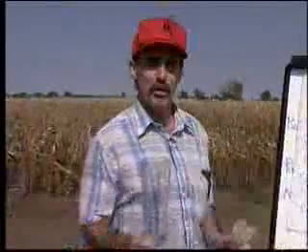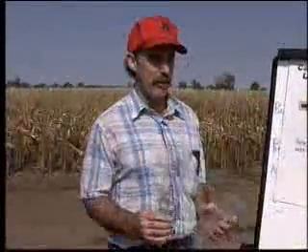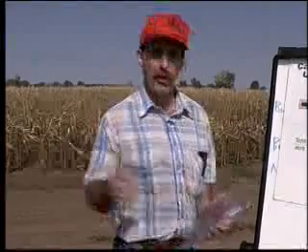A number of those along the length of the pivot at various locations can give us a pretty good indication of the application rate, and that, combined with the manure analysis, can quickly convert to so many tons or pounds of nutrient per acre. So it is appropriate to do a calibration of pivots and other application equipment, and the procedures are fairly simple.